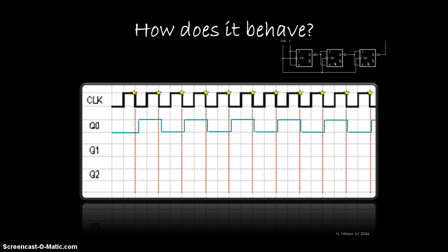Q1 is wired to toggle each time Q0 is high at a sample point. Marking in this waveform shows a frequency that is 1/2 that of Q0. Q2 is wired to toggle each time Q1 is high at the sample point. You might expect the frequency of this waveform to be 1/2 that of Q1, but it only toggles twice before it returns to a starting state of 0.